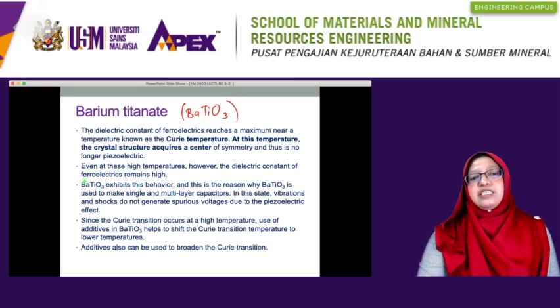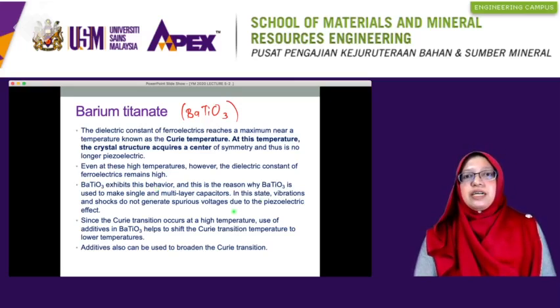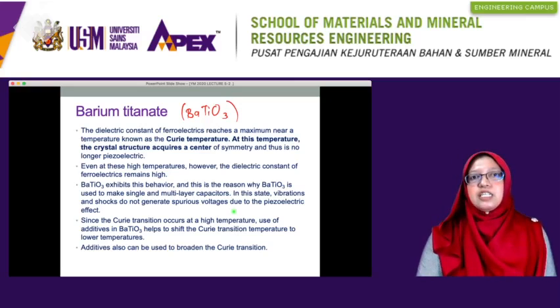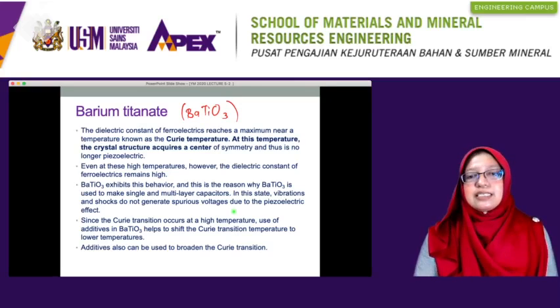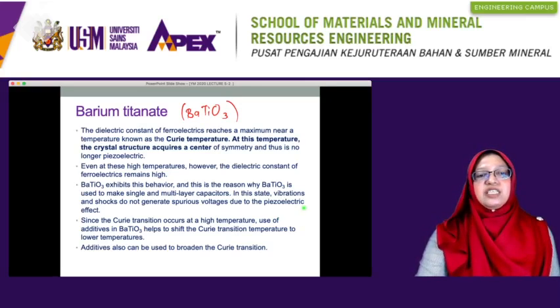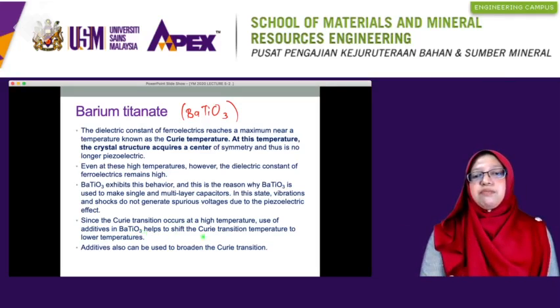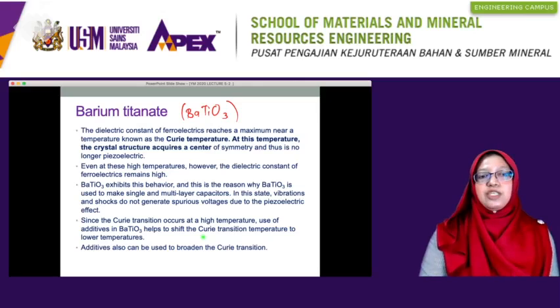Barium titanate exhibits this behavior, and this is the reason why barium titanate has been used as single or multi-layer capacitors. In this state, vibration and shocks do not generate spurious voltage due to the piezoelectric effect. Since the Curie transition occurs at high temperature, the use of additives or dopants in barium titanate could help to shift the Curie transition temperature to a lower temperature.